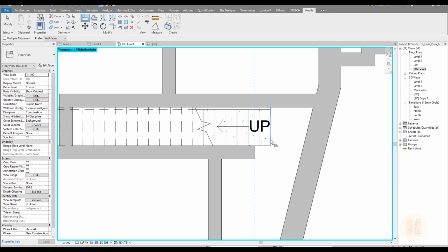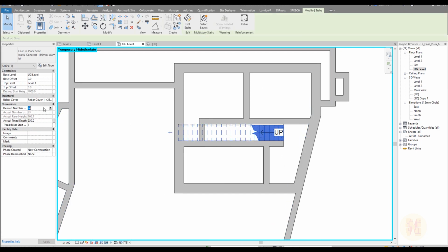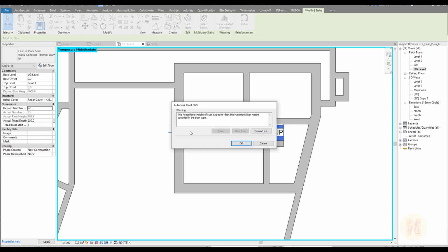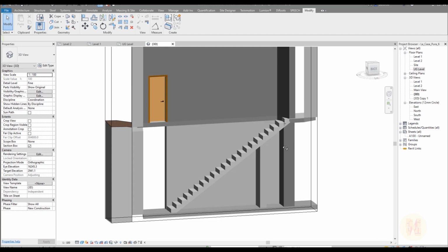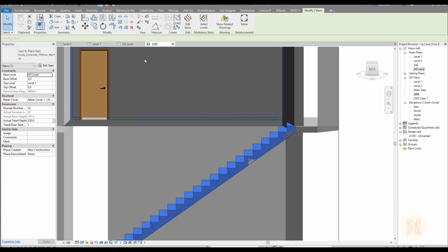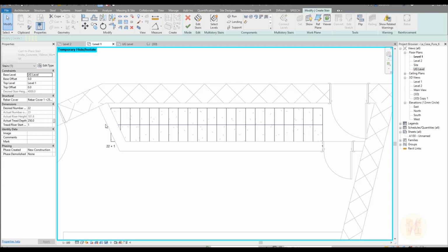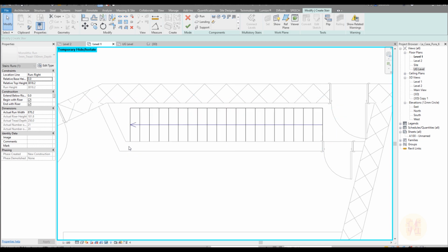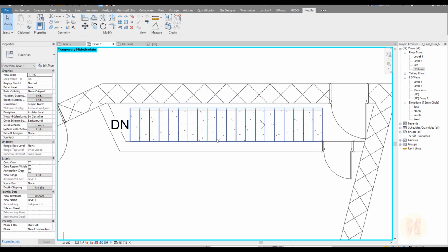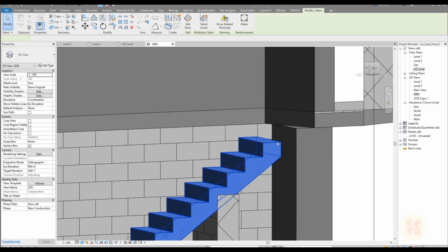Let me place it from this side. Even so, I'm ready to say this is 22 risers, as I said. Okay, let me go to 3D, and it's coming here. No, it shouldn't be coming here. Level 1, double click, select that, and let's minus even 2. Let's say okay, we'll go to 3D, and here I can place one more landing.